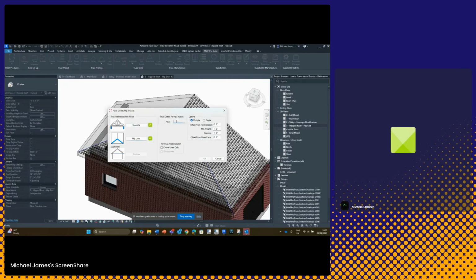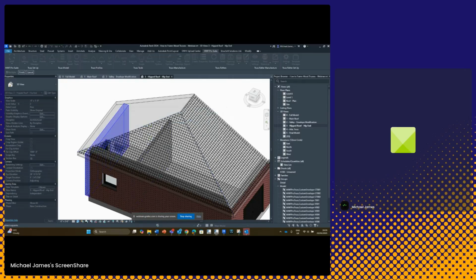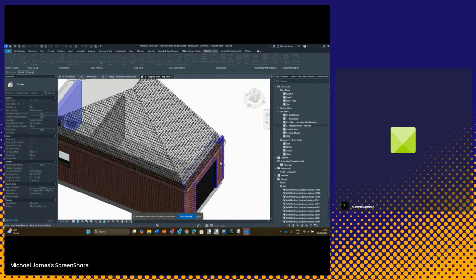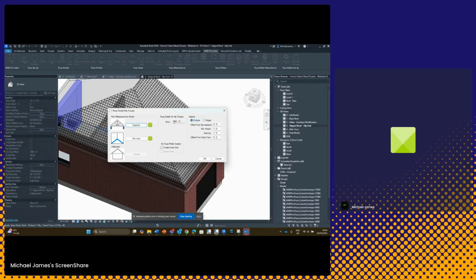What we should see here is the roof pitch. So I'm going to just go back to supports, just making sure it understands the supporting elements that I'm selecting. Okay. Once you select supports, you should always see this pop up. So if you don't, then you may have to do that process again. But you can see we've got the structural layer offset to the far side, and we're not going to add a cantilever offset. All right, so now we can see our roof pitch information here.